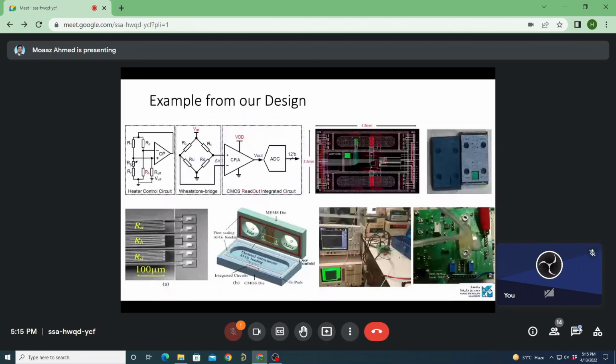At the last, I show you the fabricated die. It has these holes. Very fine diameter tubes need to be inserted for the inflow and outflow of the gases, so that we can measure that. So these holes are for that purpose. The diameter of the hole was only 500 micrometer, 0.5 millimeter. In the down right side, you will see the PCB where we do the testing. During the testing, we are inletting and outletting the gases, then observing the electrical characteristics.